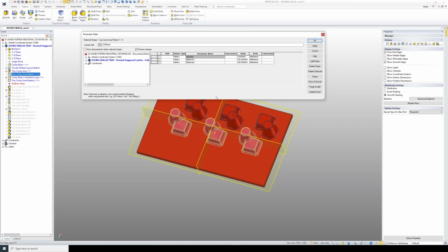I'm going to call it fill pattern, and I'll press Control C to copy, and put that in front of each of these and go apply. And now we'll create a new one, Control V and angle, and this is going to be an angle parameter, so I need to select this, and I'll leave this as 0 for now.